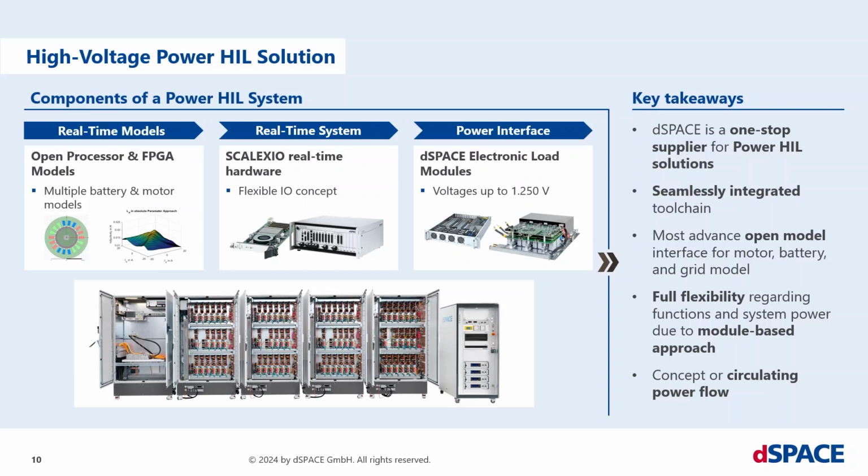The toolchain is seamlessly integrated, so you can start, for example, with these two components to set up signal hardware in the loop testing, and after a few months, if you want to increase your test coverage, you can also add the power interfaces with exactly the same models and exactly the same hardware to bring it also on a power level. And due to the fact that we offer open models, you have the full flexibility of bringing in your own ideas towards these models or use our models and only parameterize them.